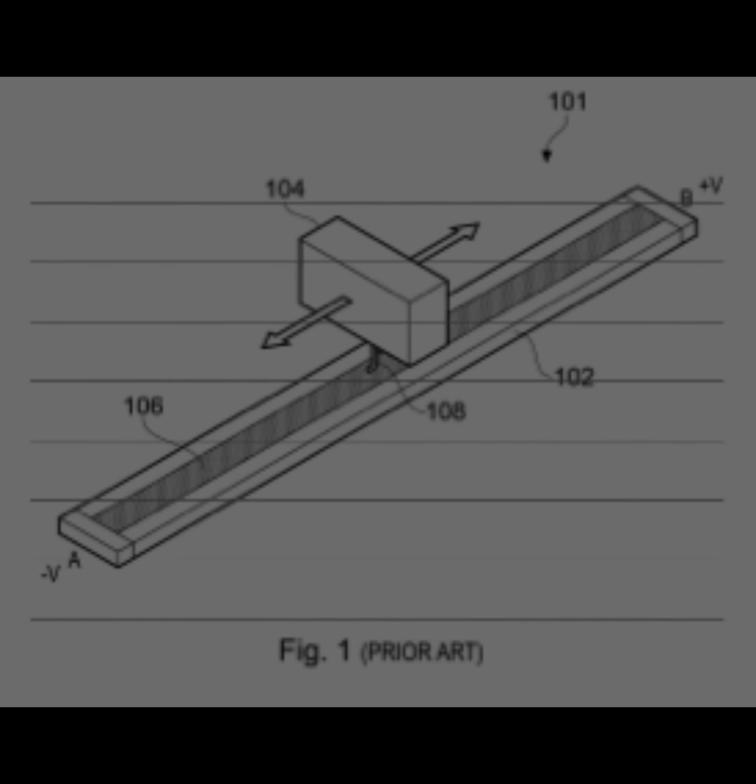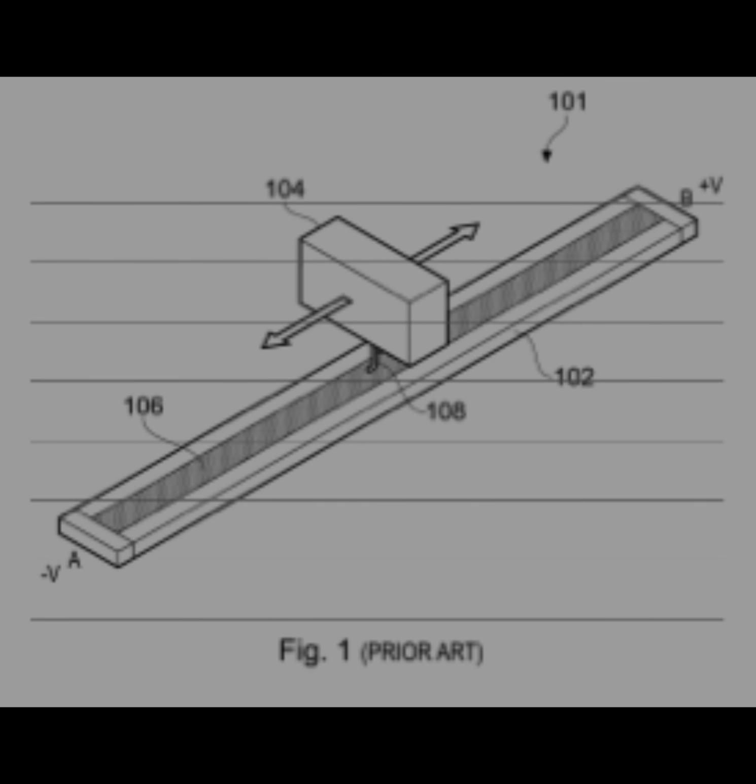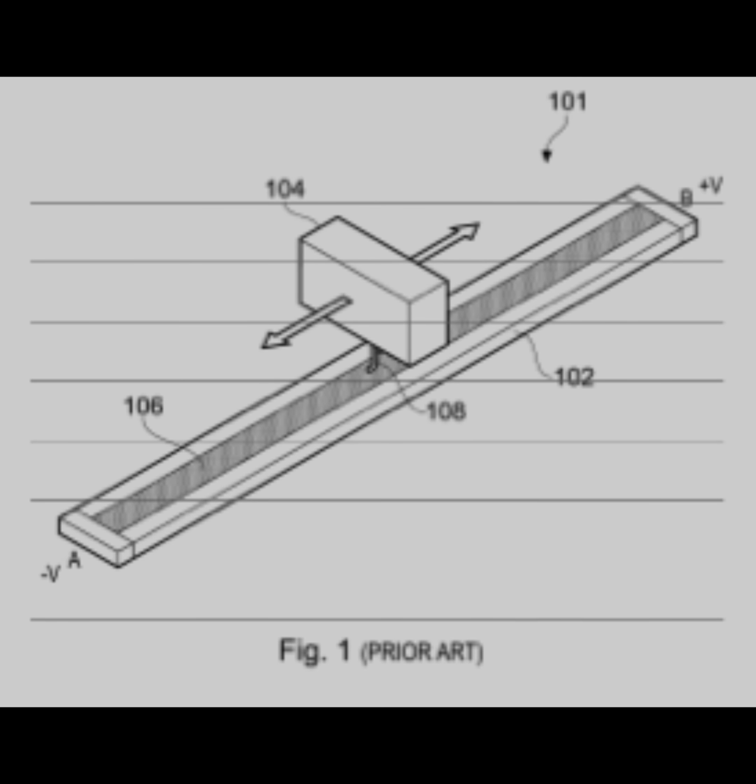We will now explain how our device functions with reference to figures 3A and 3B. A first pair of contacts, A and B, and a second pair of contacts, C and D, are provided at the periphery of the resistive layer 206. The resistive layer 206 can be connected to a voltage supply in the control unit via the contacts A, B, C, and D. The control unit comprises a switch which alternately connects the first pair of contacts and the second pair of contacts to the voltage supply for consecutive time periods, T1, T2, T1, T2, and so on.